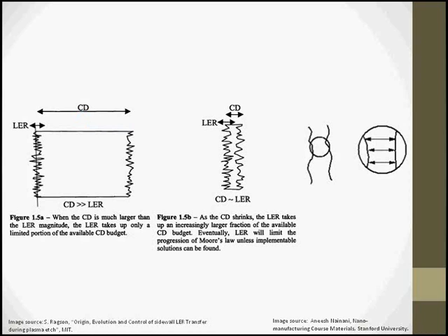In order for this line width roughness to be minimized, we need to start with a good litho mask. But the etch process can also negatively impact this line width roughness parameter. And it can do that through UV exposure from the plasma, ion bombardment that shaves off the edges, and also from heat damage. Resist typically deforms above 130 or 140 Celsius, and so if the temperature is not regulated during the etch process, that can deform the mask.